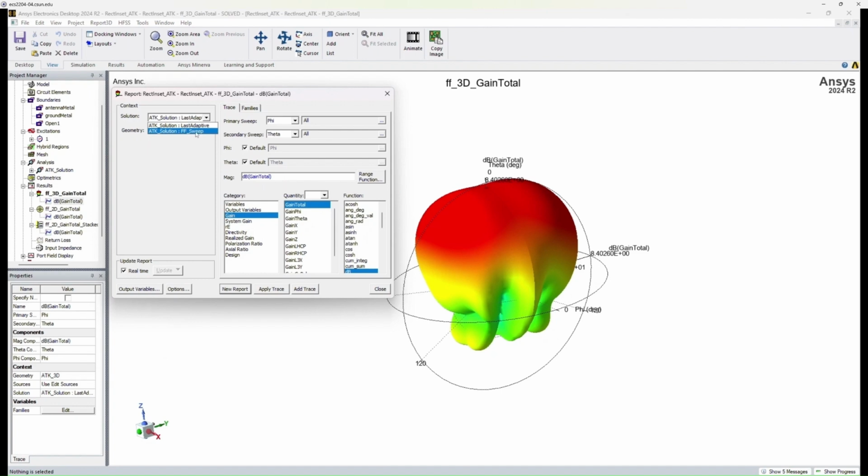This will allow us to take frequency points from that sweep simulation rather than just the one last adaptive frequency, which HFSS uses simply to build the model that it will simulate at later. The geometries are essentially combinations and definitions of angles to plot and record data in, and we can leave it the way it is for now.